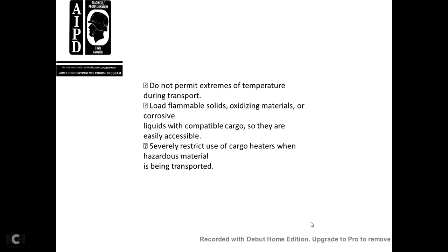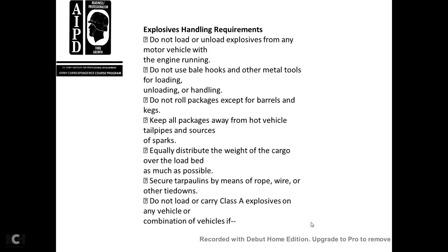Do not use tools which may damage the packages for loading and unloading. Do not permit extreme temperatures during transportation. Load flammable solids, oxidizing materials, and corrosive liquids with compatible cargo so they are easily accessible. Restrict use of cargo heaters when hazardous material is being transported. Explosive handling requirements. Do not load or unload explosives from any motor vehicle while the engine is running. Do not use bale hooks or other metal tools for loading and unloading packages.